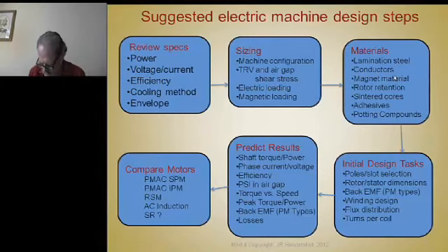The semiconductor industry, namely companies like Intel, who've been packaging transistors and microprocessors for years now, has a similar problem. There are millions of transistors in a microprocessor, and the density is so high that they are not able to extract all of the heat generated by the constant switching of the gating of these transistors. They're not able to extract all the heat from the metal plate on the bottom of the pack, so they have to take heat off the top of the pack, which is encapsulated with some sort of thermoplastic or epoxy, usually thermoplastics.